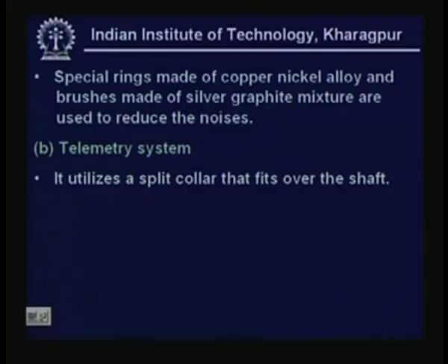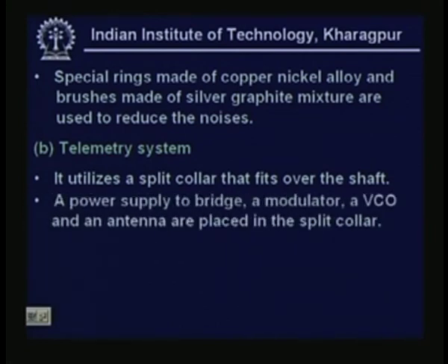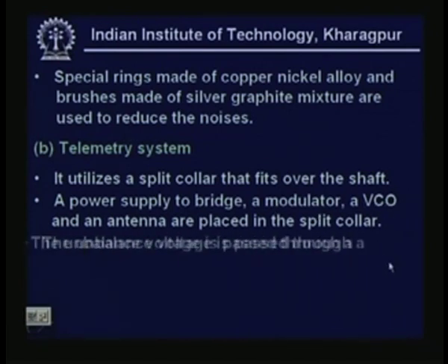Telemetry obviously means wireless telemetry. It utilizes a split collar that fits over the shaft, and a power supply to the bridge, a modulator, a VCO, meaning voltage controlled oscillator, and an antenna are placed on the split collar.